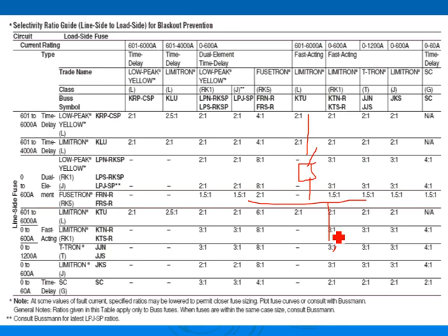The largest fuse that you're going to feed right in this area, say if this was a 100 amp fuse, the largest fuse that you should pull out of here is what? 50 amp. So the ratio is 2 to 1. The main is twice the feeder. Look at these. Almost most of them, if you use the same type of fuse, you have a good coordination. But the proper way of doing it, obviously, is to look at the curves, like I showed you, to see whether they are coordinated or not. So that's a rule of thumb.